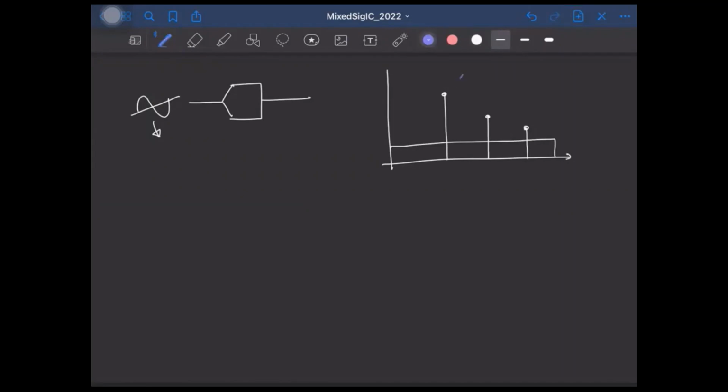So here it's quite clear what the signal component is, what the nonlinear products or harmonics are, and what is noise. So we can clearly distinguish each of them, and so we can easily characterize how much noise the ADC is adding and how much nonlinearity the ADC has.